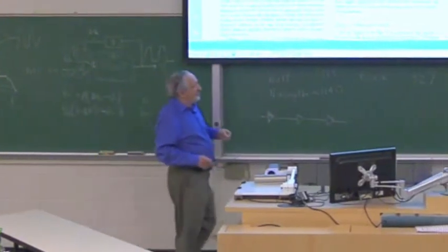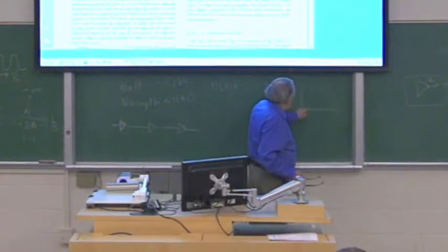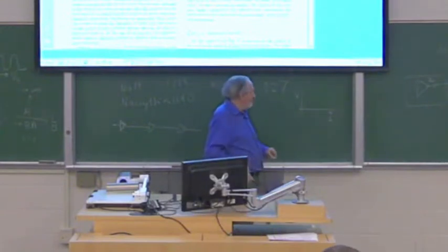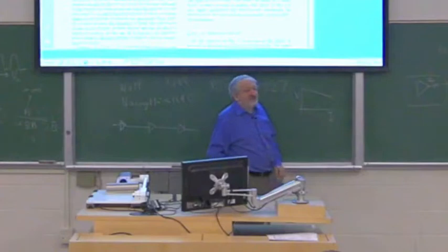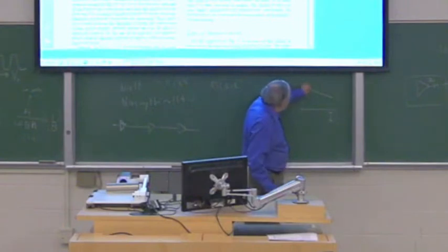So if you draw current on this axis and voltage on this one, with a regular amplifier or power supply, the more current you draw, the more the voltage drops. Think of a battery. But if you have feedback inside, you draw more and more current, but the voltage doesn't drop until it can no longer supply enough current, and then it collapses.